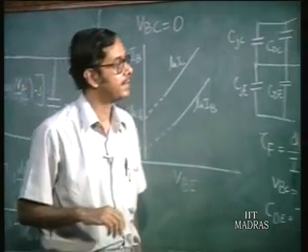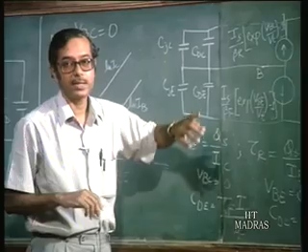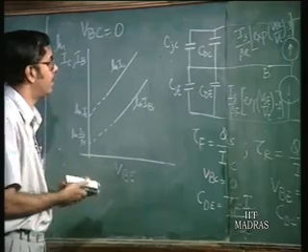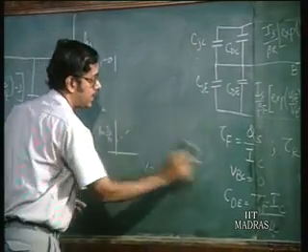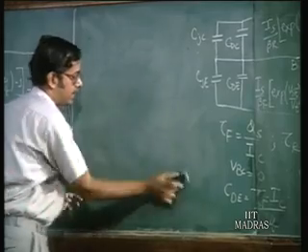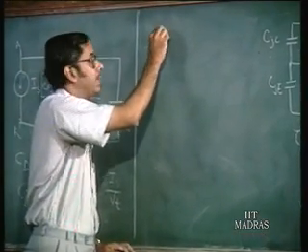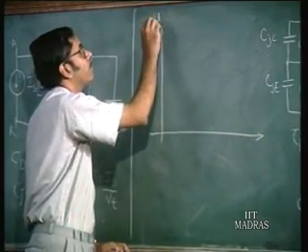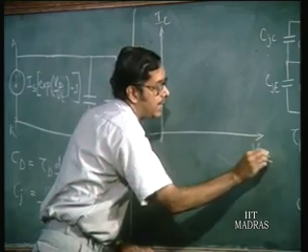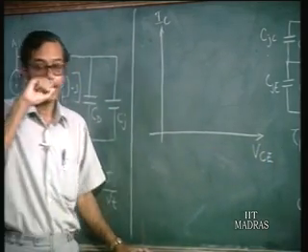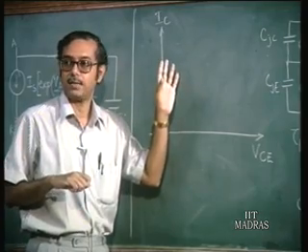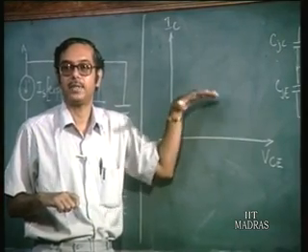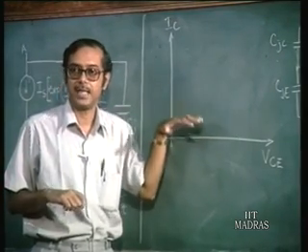So going back to the bipolar transistor, if we look at the current voltage relationship, the output characteristics of the bipolar transistor, we have seen that if you plot IC versus VCE, now when VBC is equal to 0, for example, IC and IB follow a definite relation, that is IC is beta times IB.